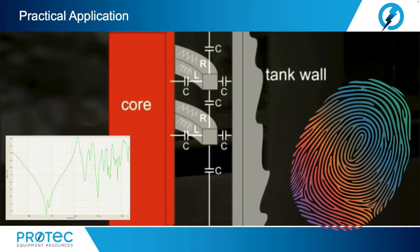Another method utilizes type-based comparisons between sister transformers with the same design. And lastly, a construction-based comparison can, under certain conditions, be used when comparing measurements between windings in the same transformer.